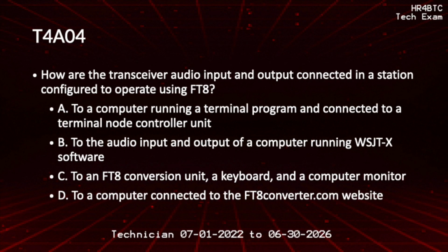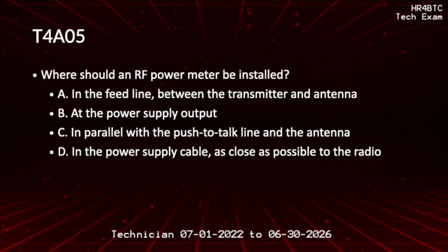How are the transceiver audio input and output connected in a station configured to operate using FT8? To the audio input and output of a computer running WSJTX software. Where should an RF power meter be installed? In the feed line, between the transmitter and antenna.